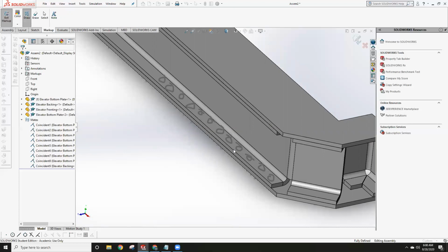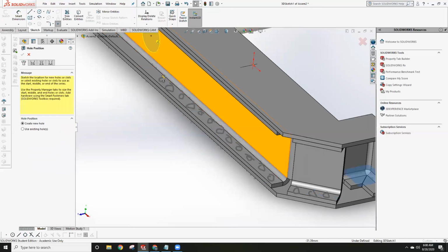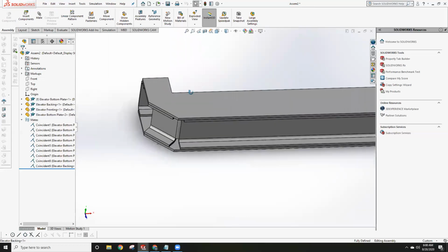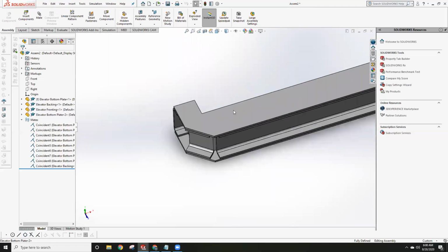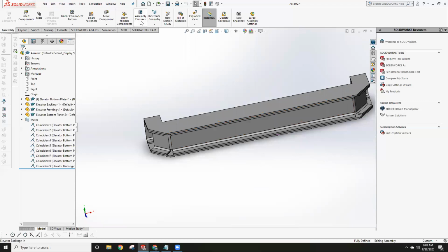When you make these, I would recommend putting them in the most complicated part, like this piece, because it's really hard to dimension everything out. And then I would go in and go to assembly features. I'd do a whole series, and I would just whole series the entire thing, and then you can do it through all or both or whatever, because it is horrific trying to align the holes. It's like what we just did, but a million cajillion times worse. It's absolutely brutal. So I would just make a whole series. Then all you have to do is change the holes on one part to change the holes on all the parts. Isn't that much nicer? Yeah, that's what I would do, because it just makes your life a whole lot easier.